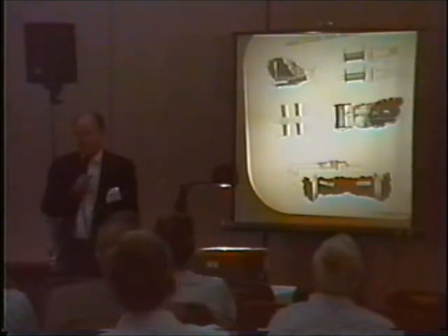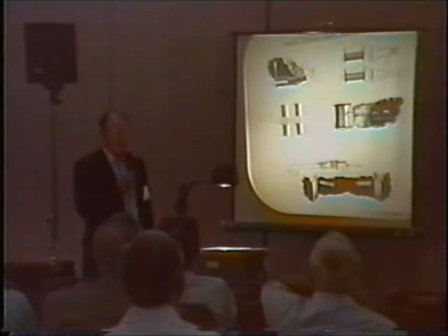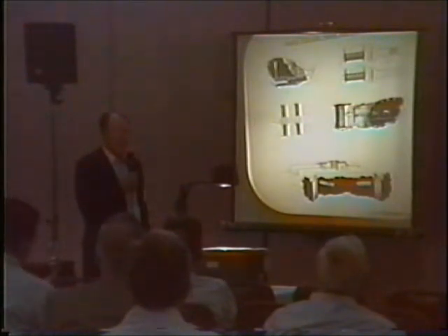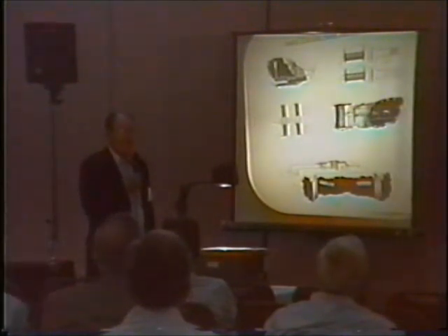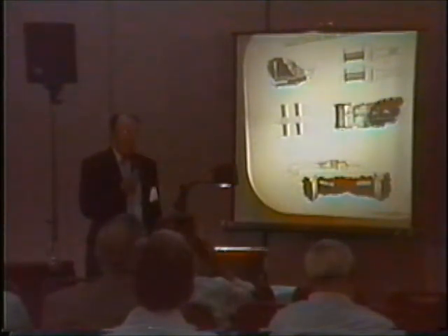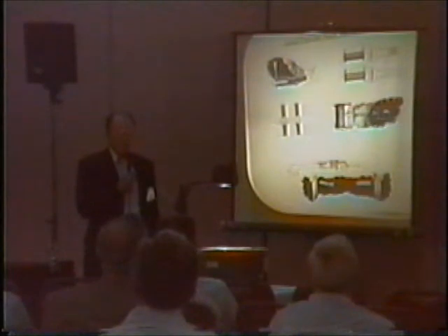What's he doing on figure 2 up there at the top? Between the left coil and the right coil, there's something in between. What's that? The tall thing in between there is a capacitor, or a capacitor bank. See, these are actually Tesla's drawings. You're looking at something that Tesla himself actually drew. What is the spark gap for? The spark gap actually controls the level of energy that's passing through. You can do it without the spark gap. I'm going to show you some fancy spark gaps in a little bit, real high-end commercial type spark gaps.